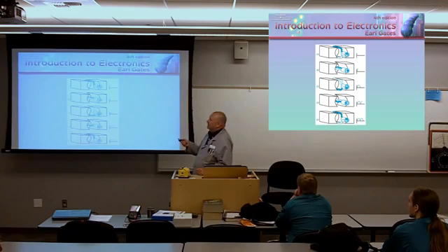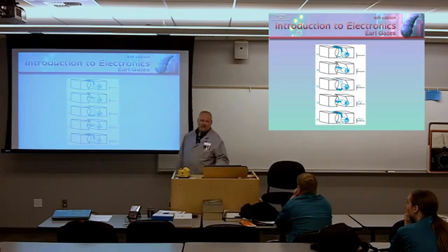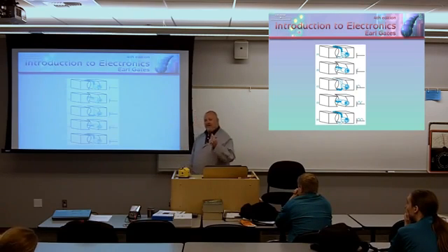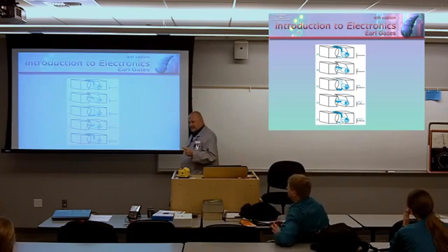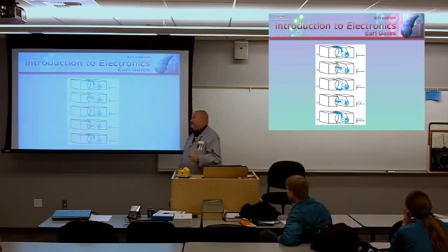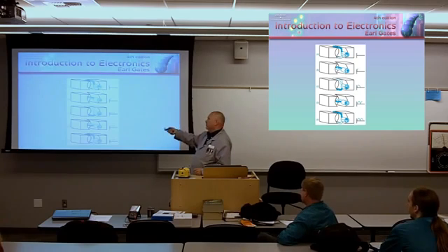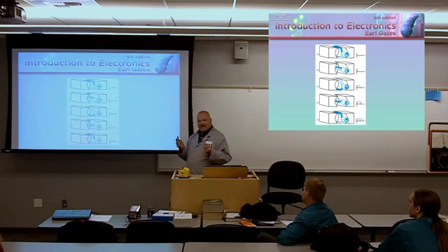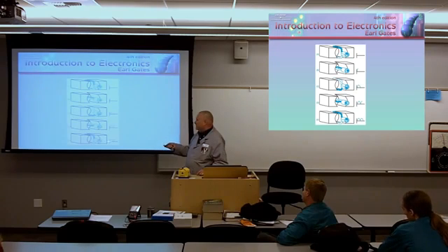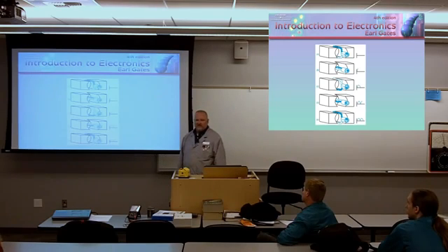Again, you've got an armature, but note here, as we rotate this, we're coming in contact here with what's called a commutator. And the commutator only makes contact for 180 degrees. So as we rotate the armature through, we're going to generate a positive pulse. Then we're going to break that electrical connection because the commutator only makes contact for 180 degrees. And then we're going to harness another positive pulse. So it's positive pulse, positive pulse, positive pulse. That's the definition of DC.